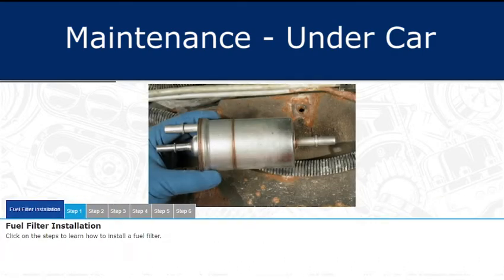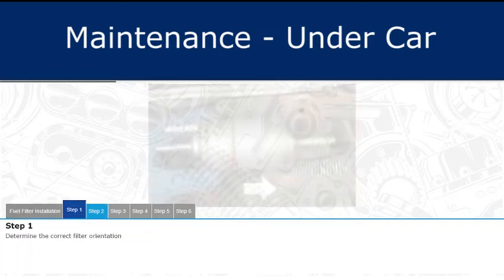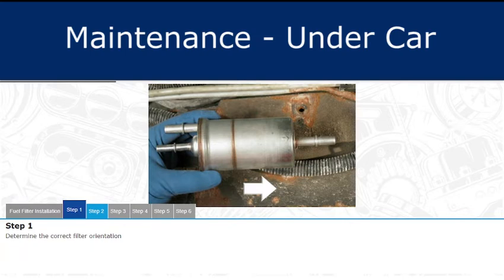Select each step to learn how to install a fuel filter. When finished, select Next to continue. First, determine the correct filter orientation. Any arrows should point toward the engine.